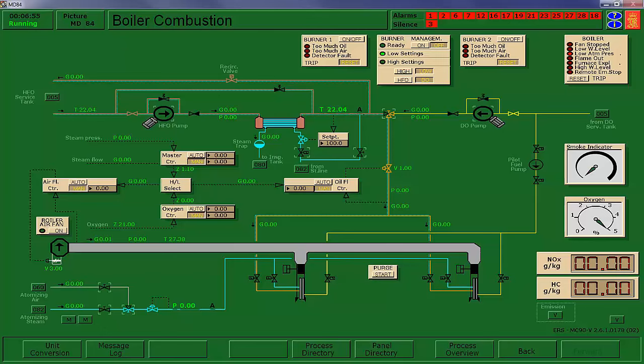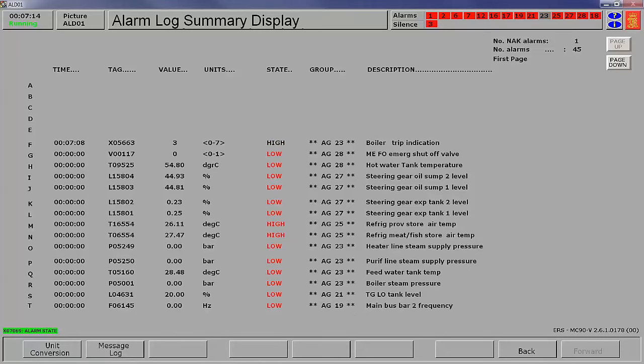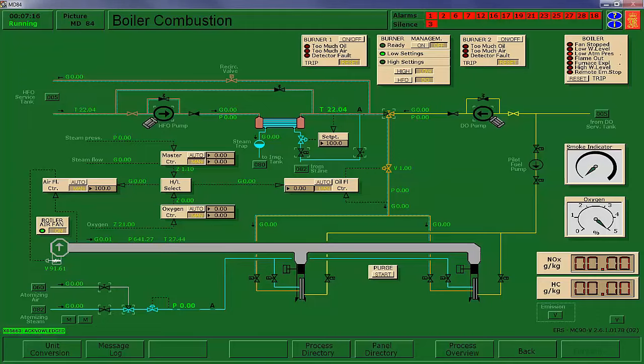I'm going to start up my boiler forced draft fan. This is the forced draft fan damper control. I'm going to go ahead and open that up 100% because I'm going to go do a purge. Okay. So this is just telling me that it's tripped, and the alarm mask was released when I started up that blower.